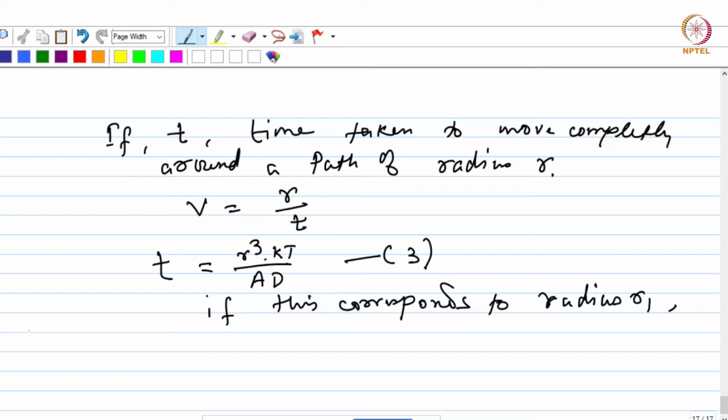Okay, but the other circles that you have having higher radius will still be active, and they will continue to supply the solute atoms to the dislocation line, right? Because as I said, there are multiple of these flow lines. So once the flow is completed along a particular radius, it will start on the next ones and so on, right? So when it is completed in a particular circle having a particular radius, it will still be active in the other circles having larger radii. Okay.